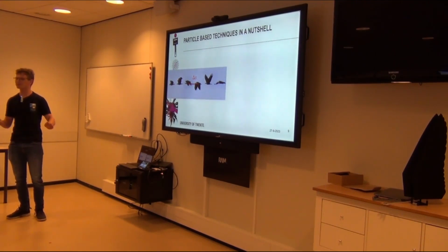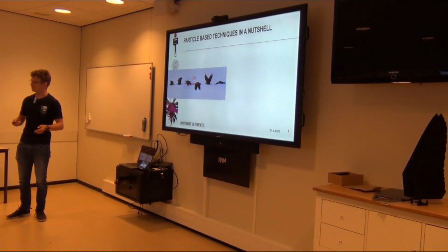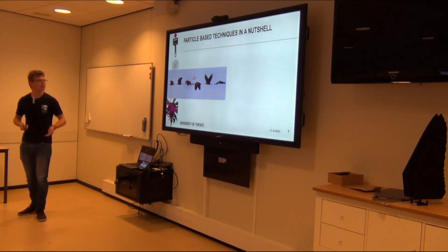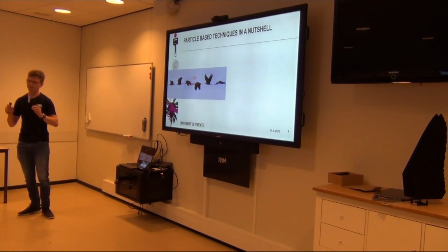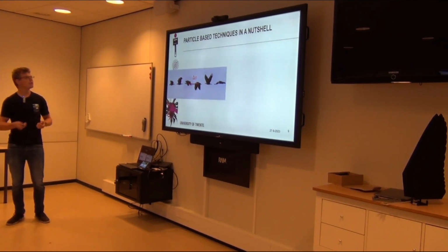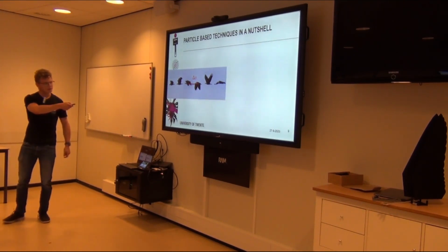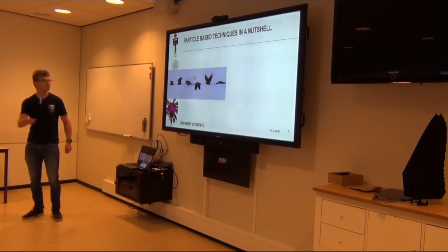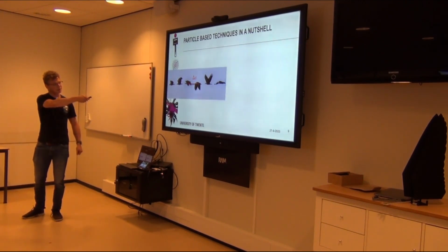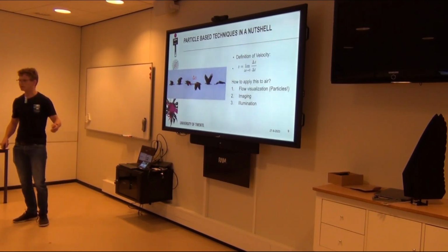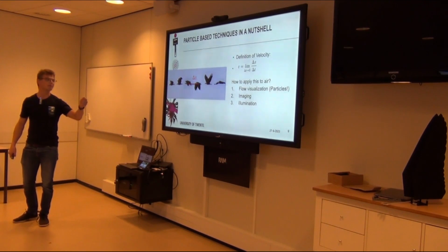So if you are not familiar with particle-based velocimetry, which is not that weird, I'll explain it in a nutshell. So let's say that you want to determine wind speed, but all you have is a camera. Then what do you need to do? Well, let's say, for example, that this series of a bird is something that you filmed yourself, and you know what the interframe time was, you know what the distance is between each different picture of the bird. Then with the simple definition of velocity, you can determine the velocity of the bird at any time.